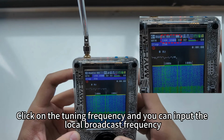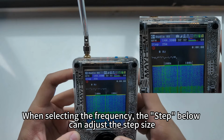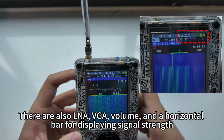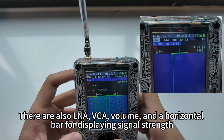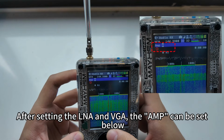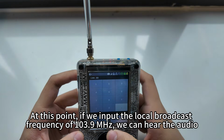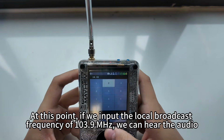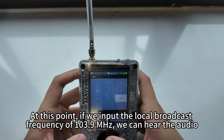Click on the tuning frequency and you can input the local broadcast frequency. When selecting the frequency, the step below can adjust the step size. There are also LNA, VGA, volume, and a horizontal bar for displaying signal strength. After setting the LNA and VGA, the amp can be set below. At this point, if we input the local broadcast frequency of 103.9 MHz, we can hear the audio.